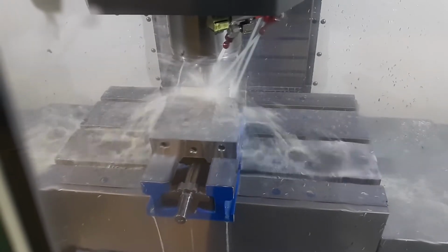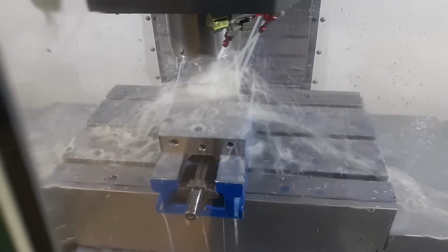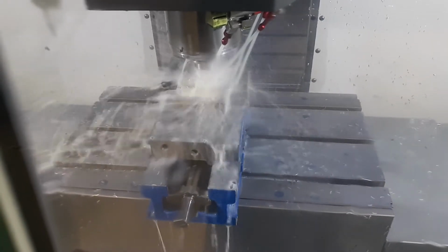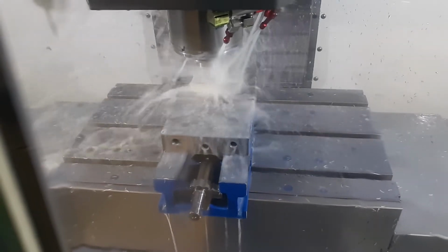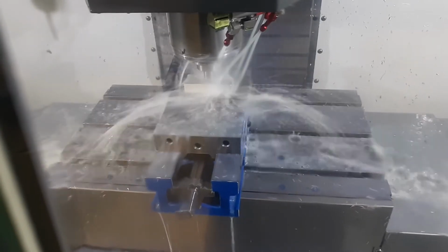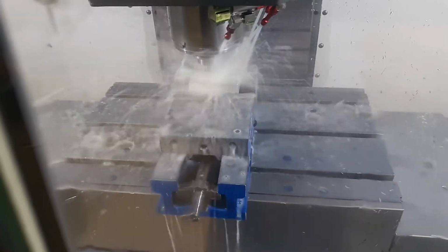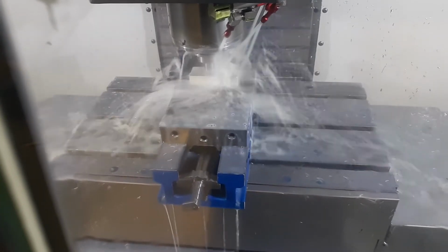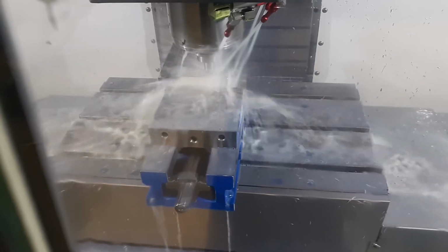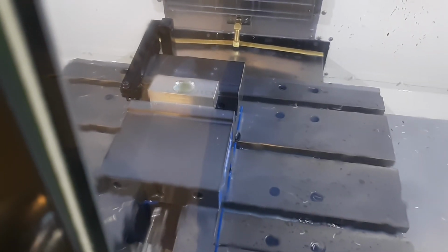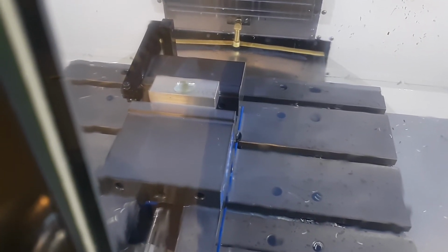But when you're doing your second and third pockets, you're going to make some changes to the I and K values to customize those pockets for the right diameter. All right, so we're 750 thousandths deep. Doing our finishing final third pass here. We'll be all done in just a moment. Alright, there we go. There's our pocket, and I know it's already the right diameter.